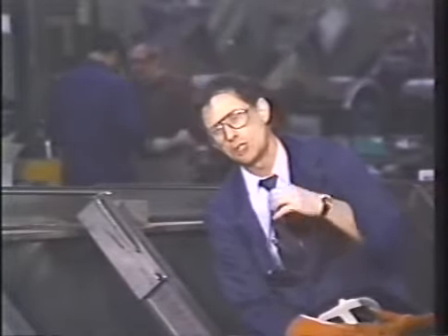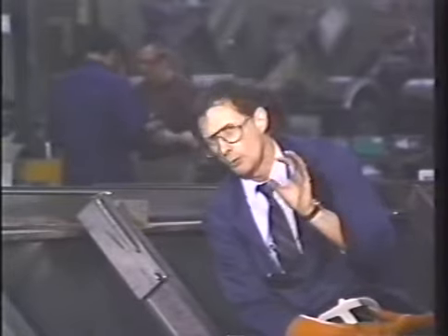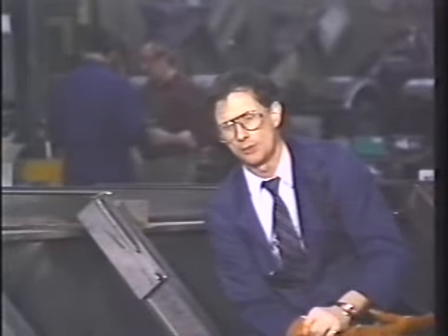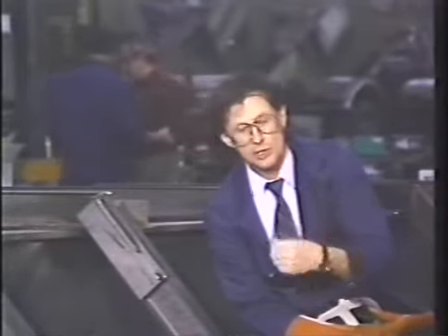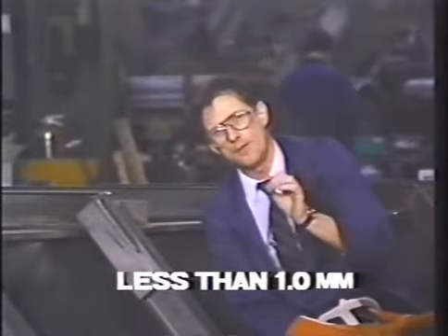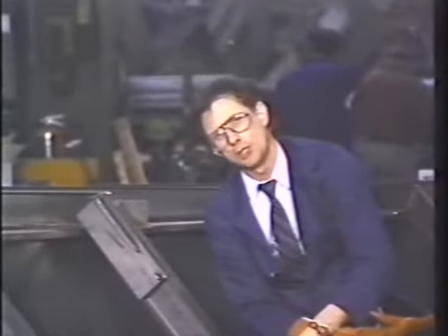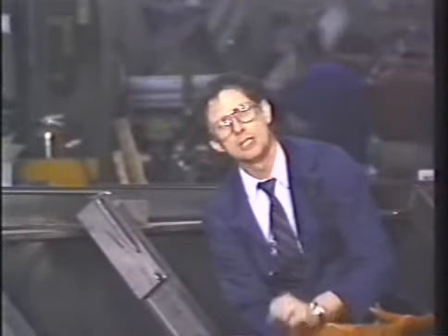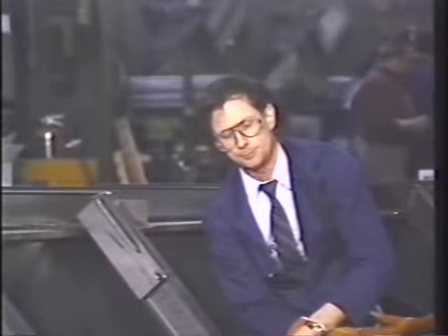But when you get into argon oxygen, you can work at 13 and 14 volts. Again, where should you use argon oxygen? On sheet metal, where you want to weld along the edge of a sheet metal, on sheet metal, say less than 40 thou, you will find it extremely beneficial to use 98% argon, 2% oxygen.